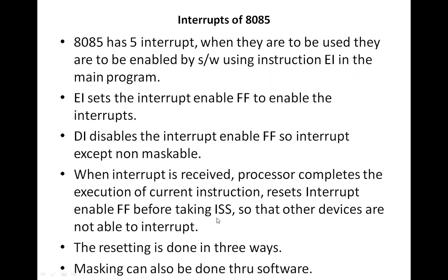Now this service subroutine is already written somewhere in the memory, at some memory location. Instead of executing the next instruction, it will execute the interrupt service subroutine.